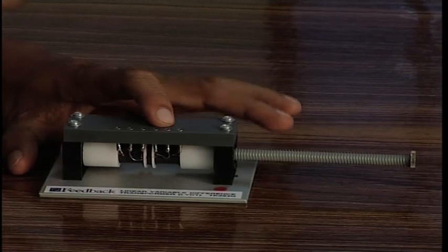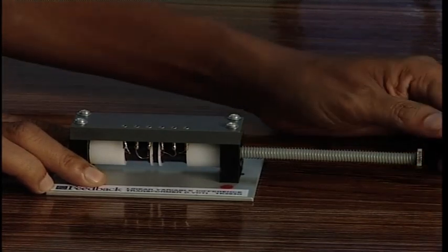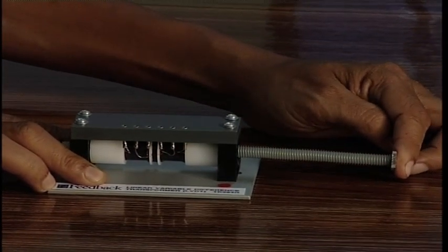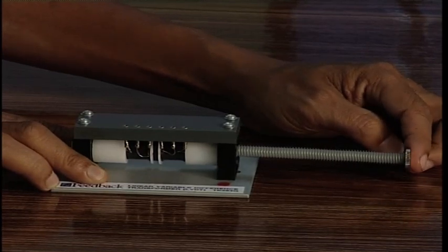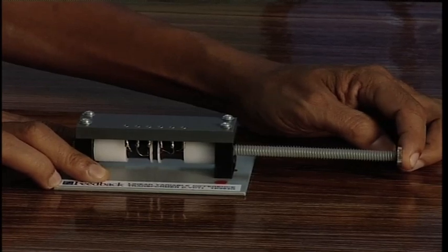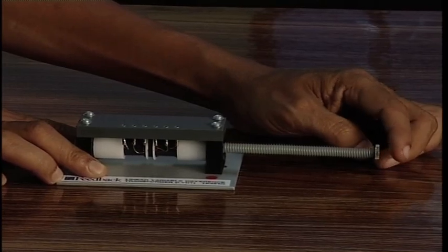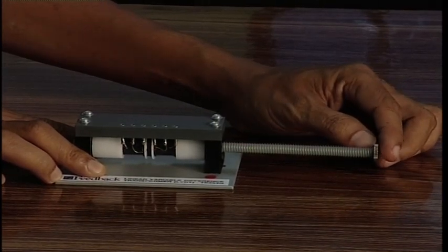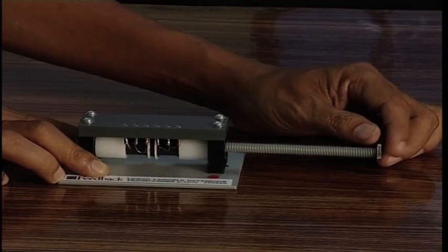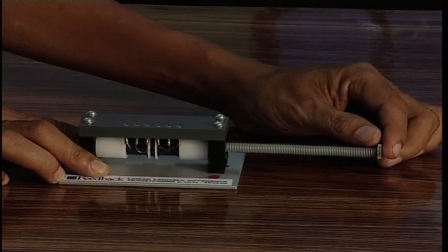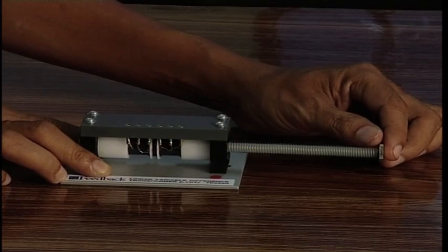You see here the core is there, a soft iron core, which will move like this. So, now I am moving, it will move like this. And then since there are 2 secondaries, if you put them in opposition, obviously you will get some output voltage. When it is exactly at the null position, the 2 secondary coil voltages will be nullified and I will get 0 voltage, but any position other than that will give you non-zero output voltage. So, LVDT we have already discussed in detail. This is actually a pictorial view of the LVDT.